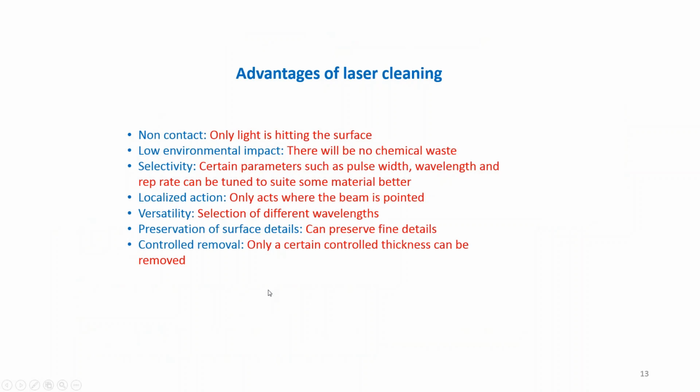Now, what are the other advantages of laser cleaning? First, it's non-contact. So the only thing that is hitting the surface is light. There's no solid material hitting the surface. Low environmental impact. There's no chemical waste. There's no dirt. There's no contaminated water to deal with.